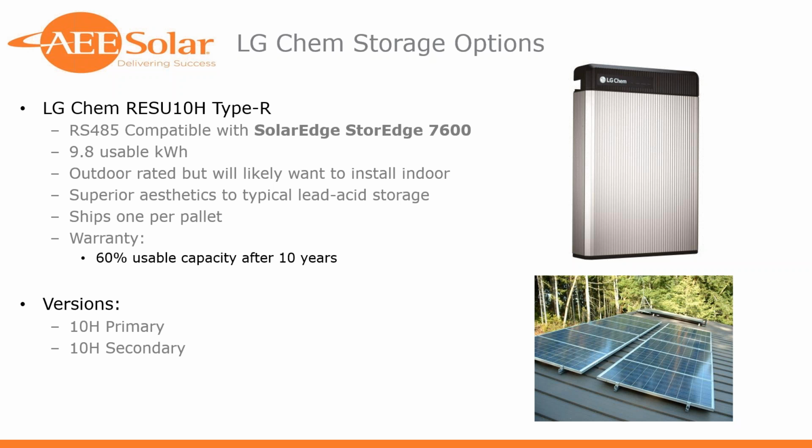9.8 usable kilowatt hours, outdoor rated, but I would strongly recommend you find a place for it indoors. Any battery is going to be sensitive to changes in temperature. They really don't like cold weather. They're not particularly keen on really hot weather either. And it's a beautiful unit. This is expensive equipment. Let's take care of our things. I'd recommend installing it indoors if at all possible. Aesthetics are relative and of course subjective, but I think it beats hands down anything you're going to be able to put together in the lead acid space.